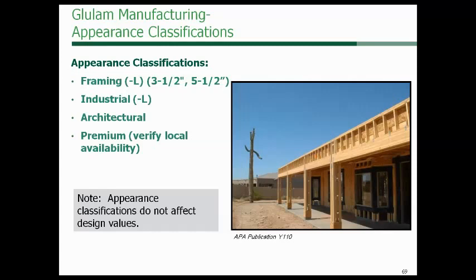Now, one thing about the appearance classification is that it does not have any effect on the design values of the glulam. So given a stress class, an architectural glulam beam and a framing glulam beam from the same stress class will have the same structural design values. They just would probably look a little bit different.